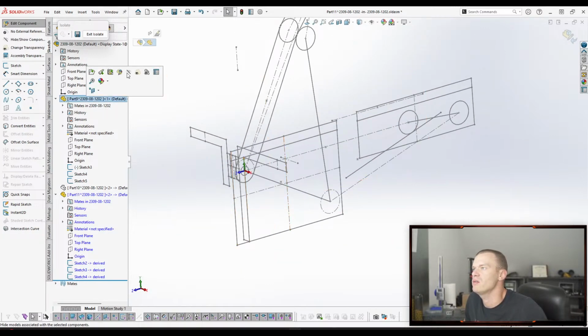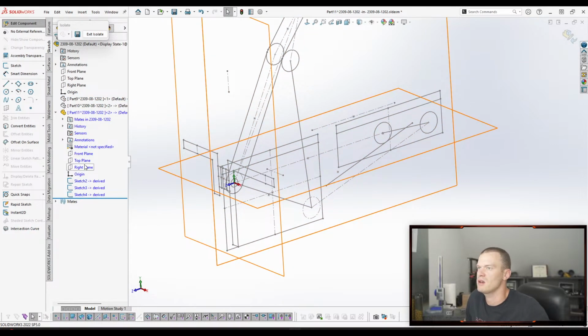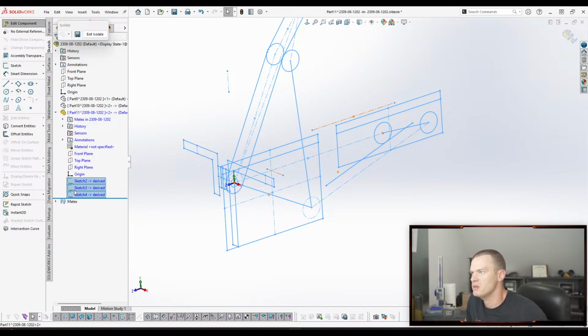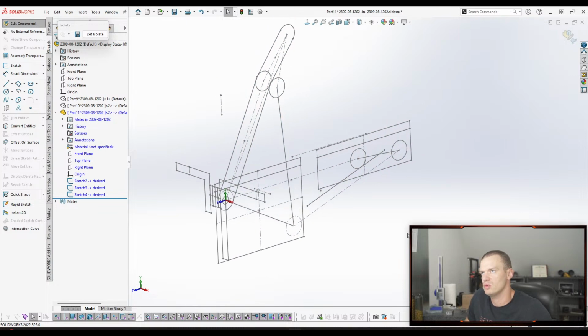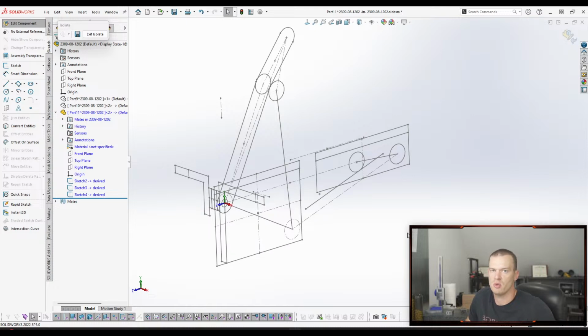All right, so now that we have all of our skeleton sketches in place, now we can start creating some geometry. So standard practice of doing a skeleton sketch technique is to try and keep these derived sketches in the top of your tree, so that if you go back and make edits to the part in the future, or somebody else opens up your work, as long as you guys are using a similar workflow and rules, it's very easy to open up a part and say, okay, that's what's controlling this part. It's kind of like an indicator.